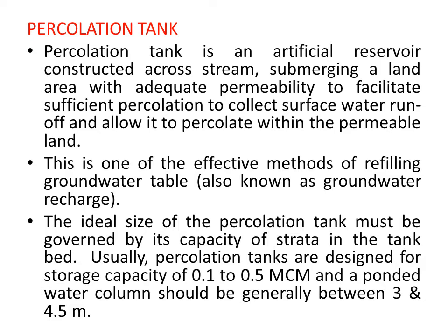So, a percolation tank is a structure created to store the runoff, and the soil characteristics are such that it has sufficient permeability to allow the water to percolate and to enrich the groundwater. This is one of the effective methods of refilling the groundwater table, also known as groundwater recharge.